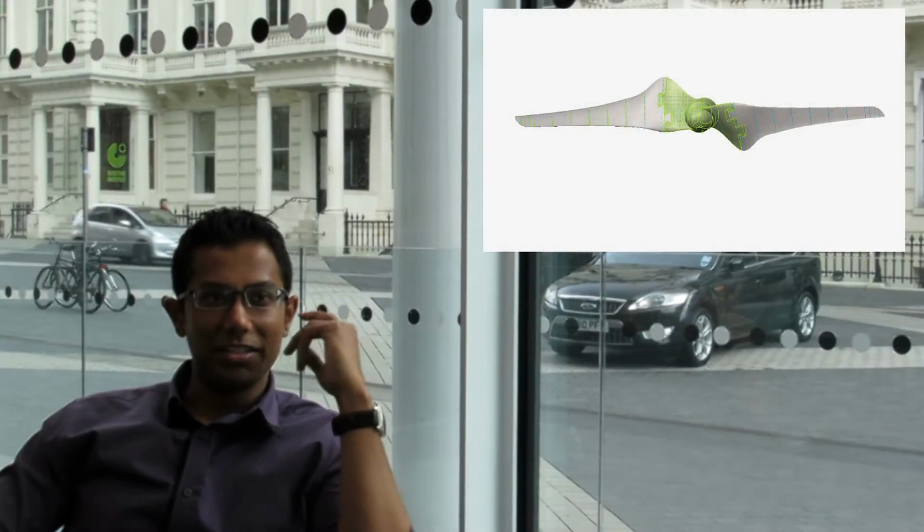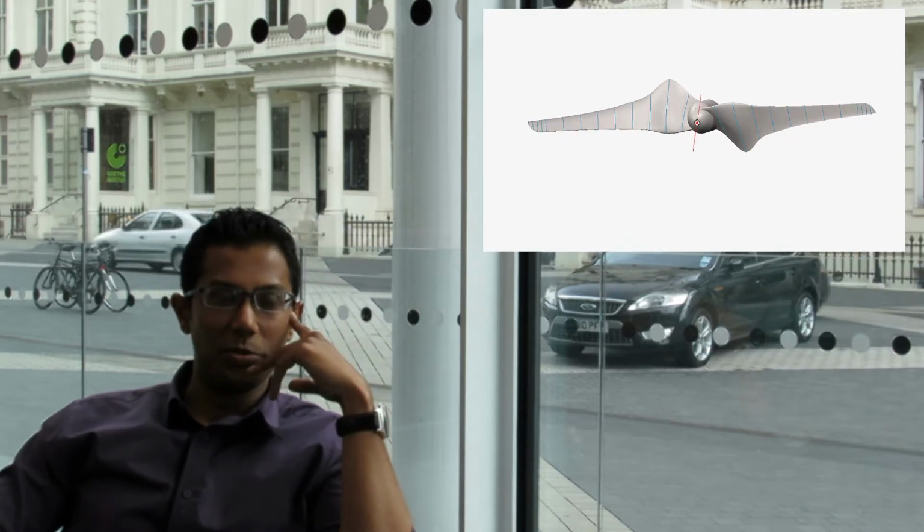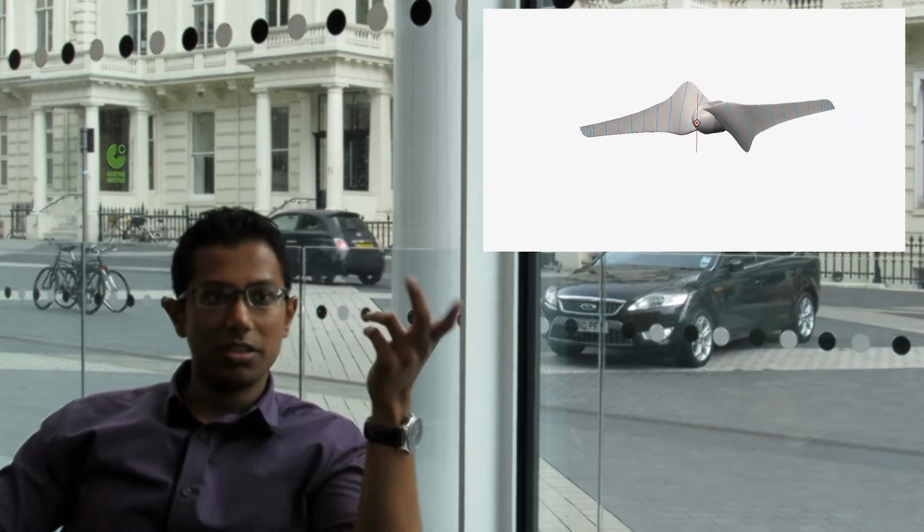We modeled the blade design using the CAD program Creo Parametric 2 and the blade geometry we had calculated earlier. Using this CAD model, we measured various parameters that we would need for our structural analysis, such as cross-sectional areas and moments of inertia at the various radii.